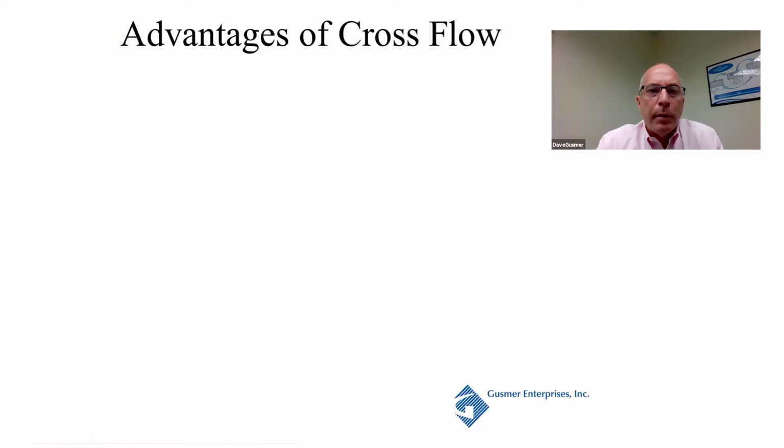So why is Crossflow popular? The number one advantage is it's one-pass filtration. If you're using DE, if you're using filter sheets, or bag filters, think of how many times you need to set up those filters. You may have a coarse, polished, sterile filter sheet. You may even have a fourth one. And with Crossflow, you're only moving it one time. You've gone from 3 steps to 1.